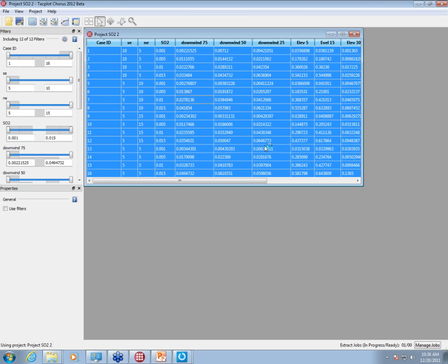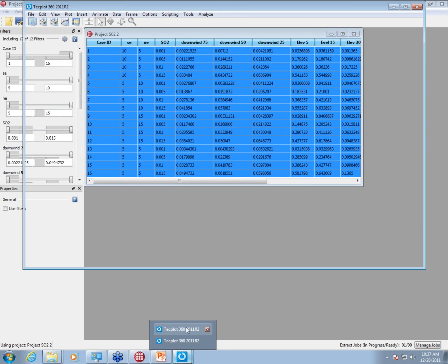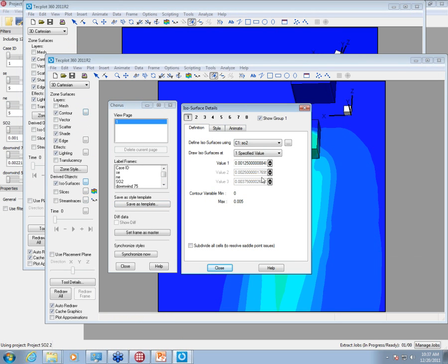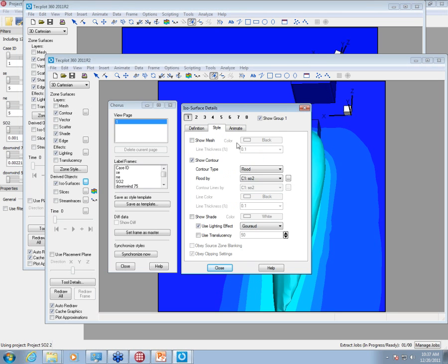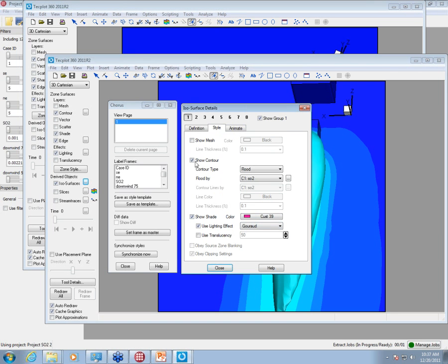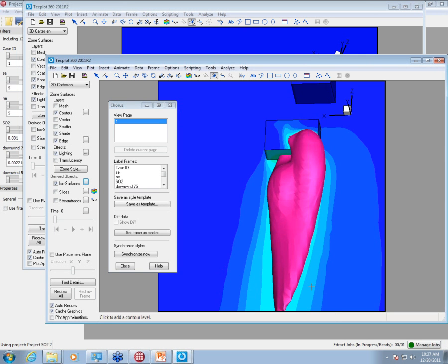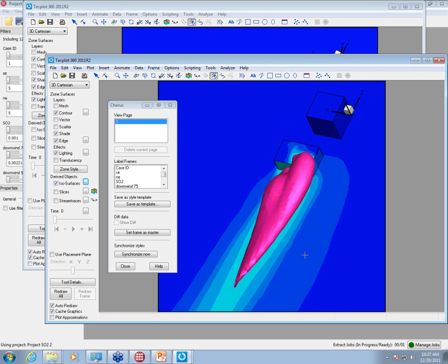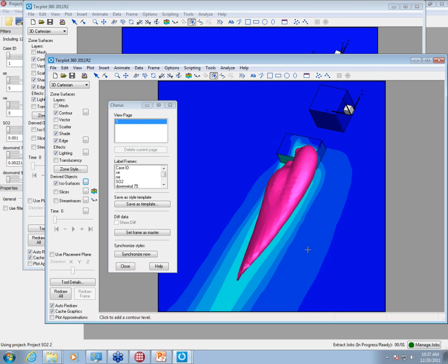In fact, let's make it ever so slightly more interesting by putting on an isosurface, something a little more interesting than this. You can see the small isosurface there. I'm just going to change the concentration and go down 2 orders of magnitude. From a style perspective, we're going to change this to just show red, or in this case, pink. This is good enough. Pink is bad. You don't want to find yourself there, if at all possible, because it will get you quite sick. Stay out of the pink gas, if at all possible.